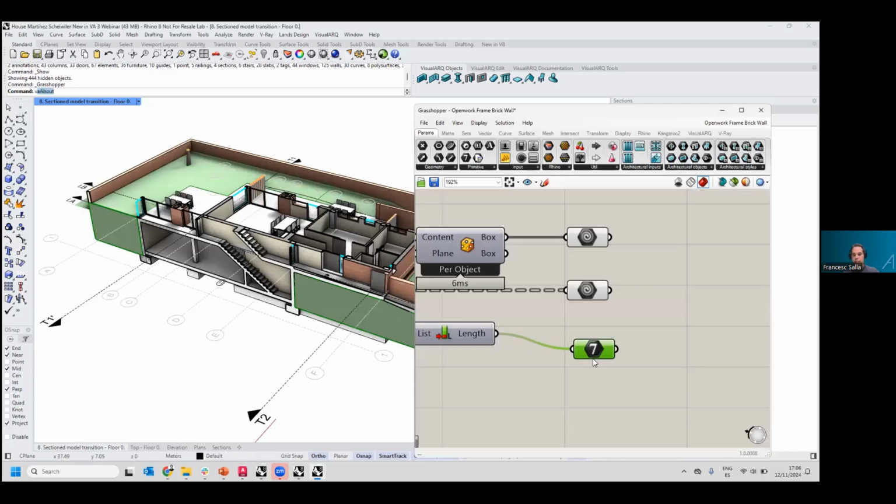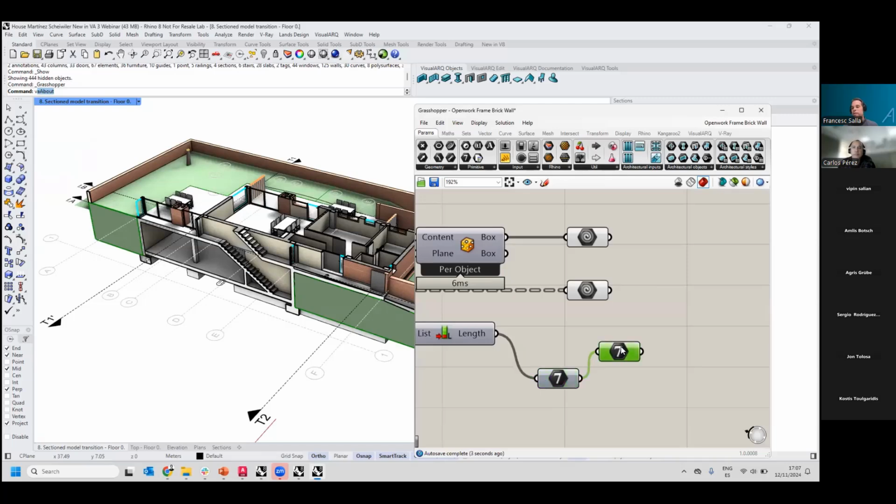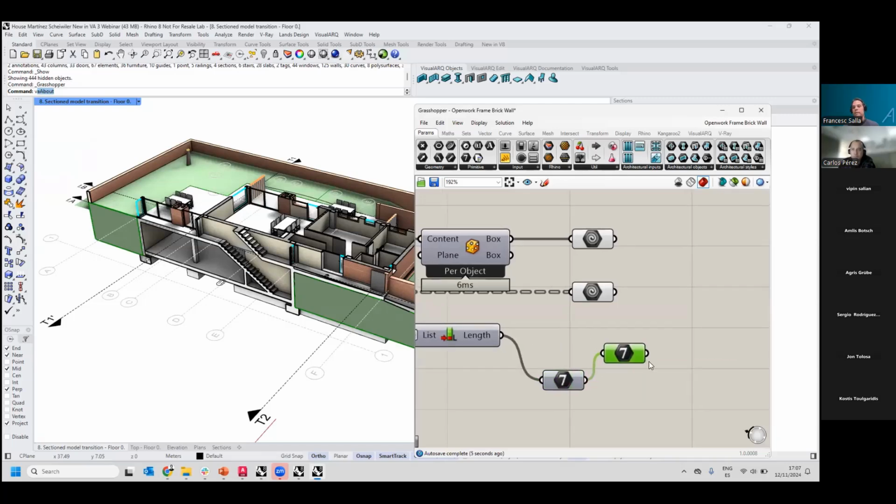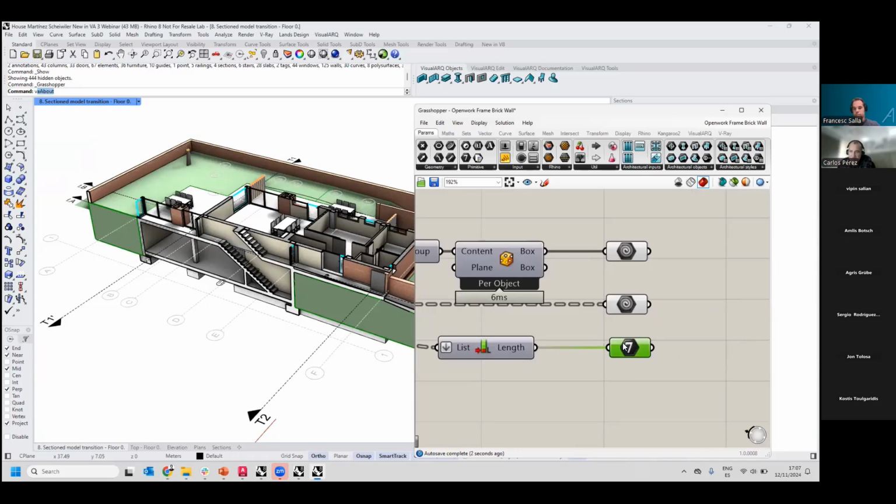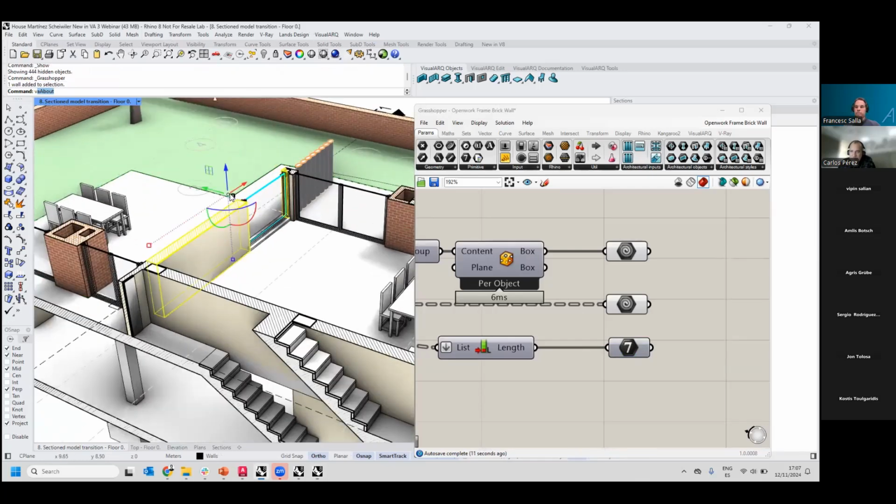But if we had this duplicated, and we connected this in here, this one would not be identified, but only this one. So it needs to be ending geometry, integers or numeric values that are not connected to anything else. And same for the geometry output parameters. Okay, what else? Do the area and volume calculations for walls account for openings? Yeah, of course. The volume of walls takes into account the openings of doors and windows to calculate the area and the volume.